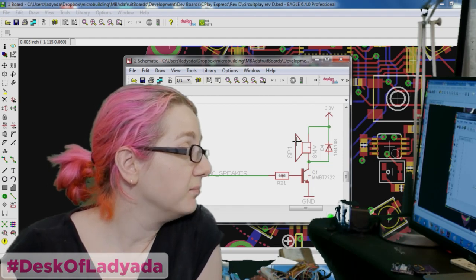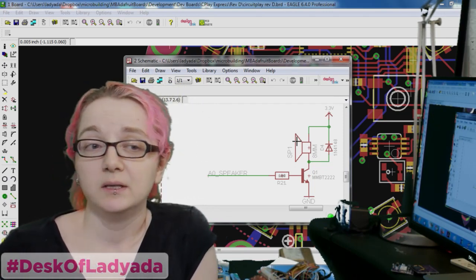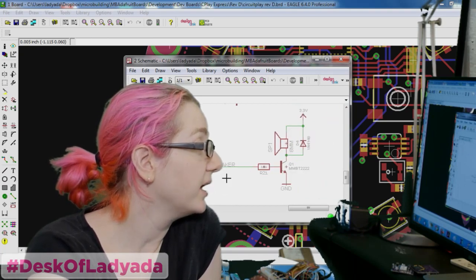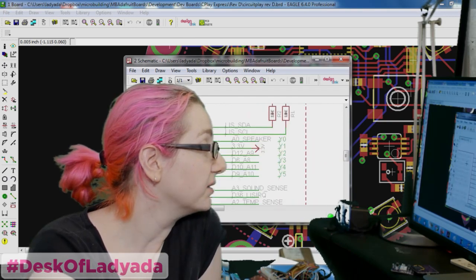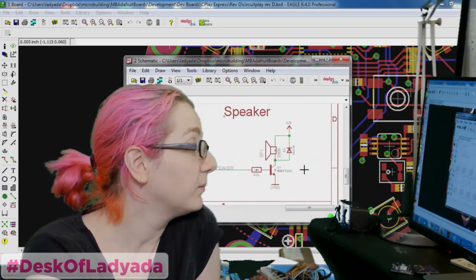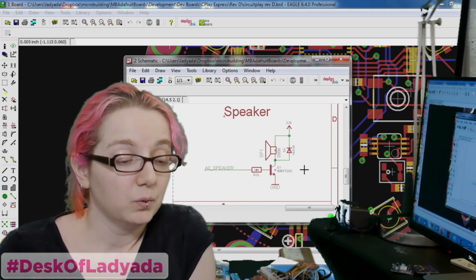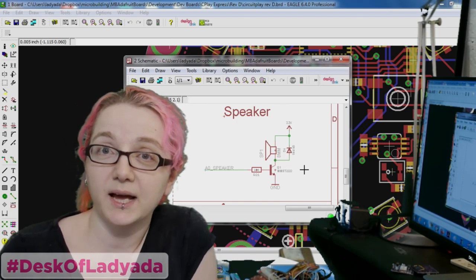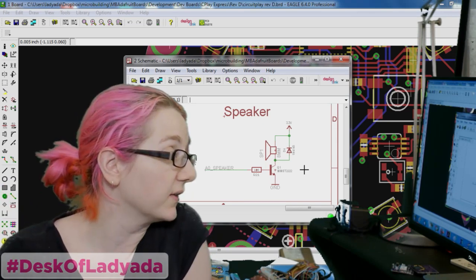But I thought that maybe I could upgrade the speaker. One, I could use a slightly larger one, because on the SAMD board I have A0, that's the pin I'm connecting this to, and this pin is actually a V out, it's a DAC. You get a 10-bit DAC on here. Whereas the previous Circuit Playground, which was a 32U4, didn't have any way to do serious audio out, because it didn't have an analog output. You could PWM it, but I decided I'm going to start with a transistor and see how that goes.